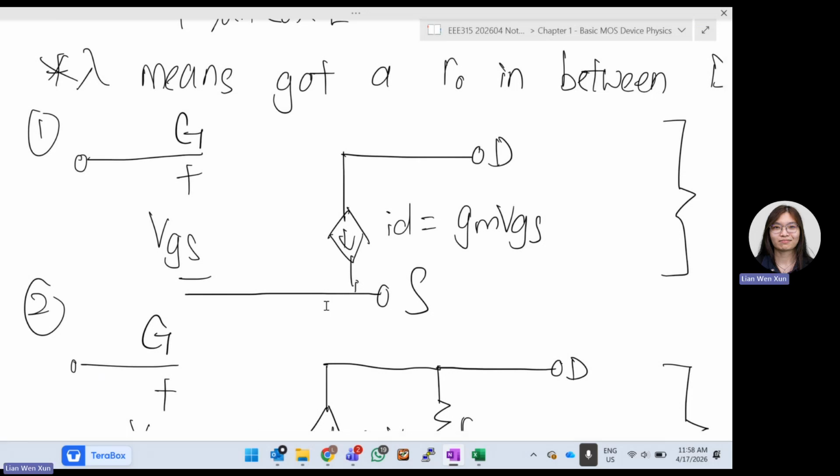And then we know voltage allows the current to flow from drain to source. So it will be a current source already. Your transistor is basically a current source. So we need to draw a current source. This is a current source symbol that connects from drain to source. We call it ID. Okay, this is the current flowing.